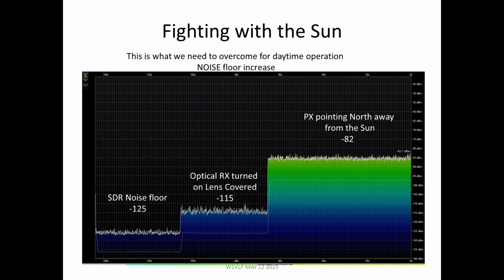The rate I chose was to stay away from audio, because I didn't want the detectors detecting the second, third, fourth, fifth, sixth, seventh, 10th harmonic of 60 hertz or 120 hertz or God knows what. So many things make noise. Mine runs around, I think, 16 or 17 kilohertz.